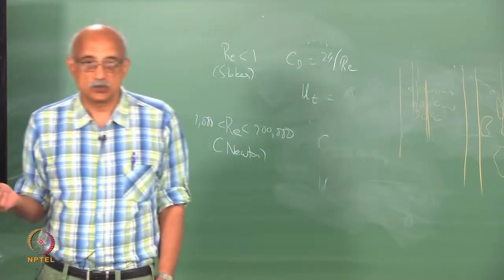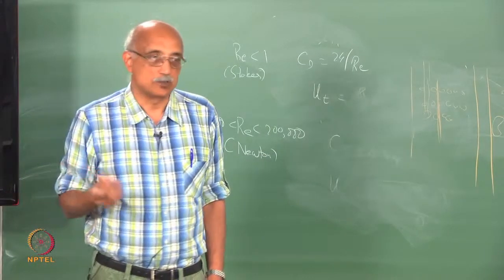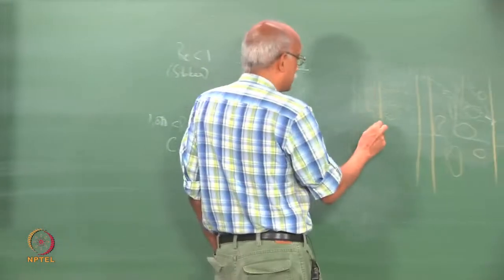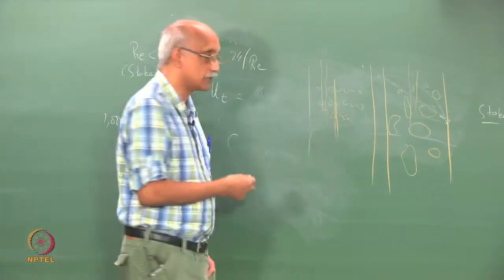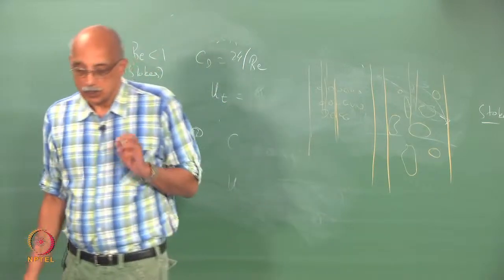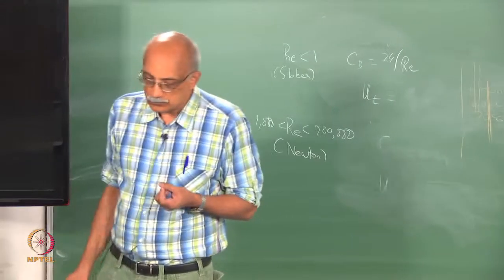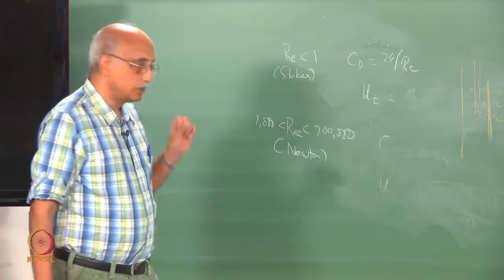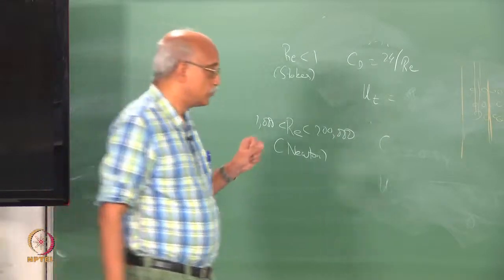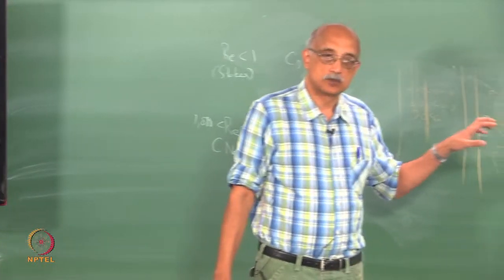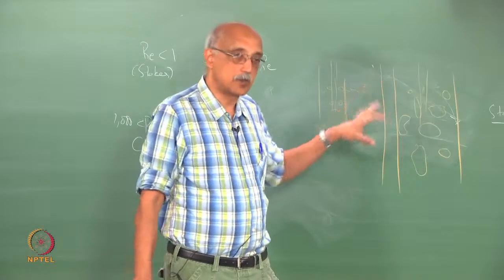However, once you get into the fluidized mode, the difference between a bed that was originally packed with spherical particles and a bed that was originally packed with non-spherical particles tends to be very different, because now what you're really looking at is the flow characteristics of particles in a fluid. In other words, now the particles are in motion.